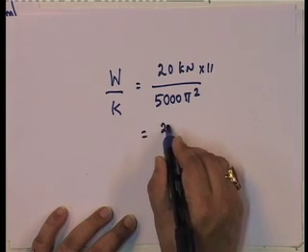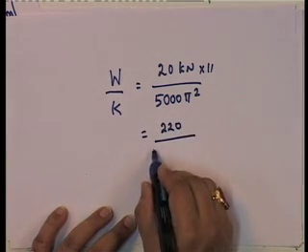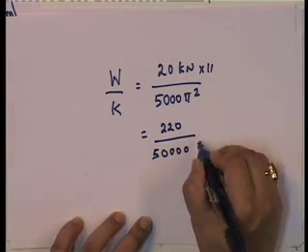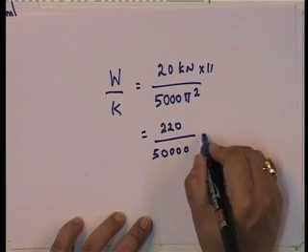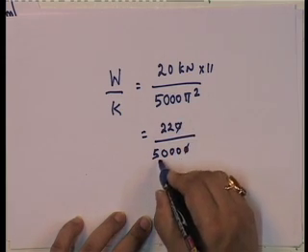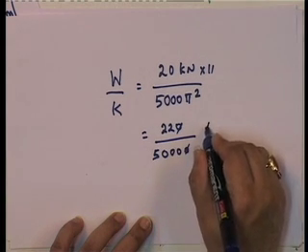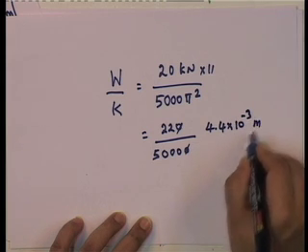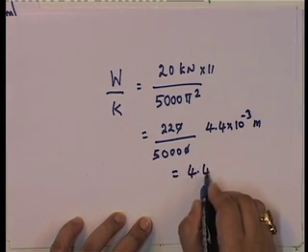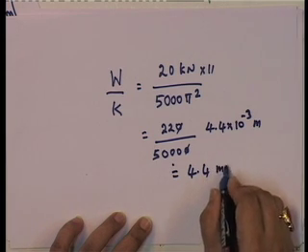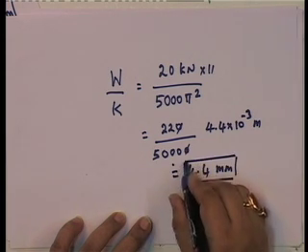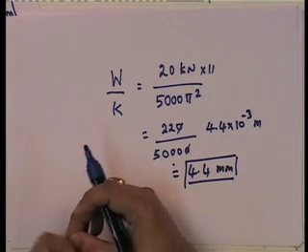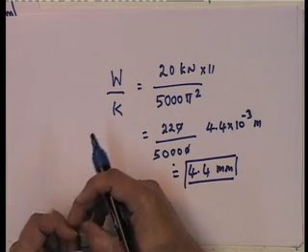You can do a much better computation if you want. And so, this becomes 4.4 into 10 to the power of minus 3 meter, which essentially means approximately 4.4 millimeter. That is not a very soft spring. A 2-ton mass is only transmitting 4.4 millimeters.